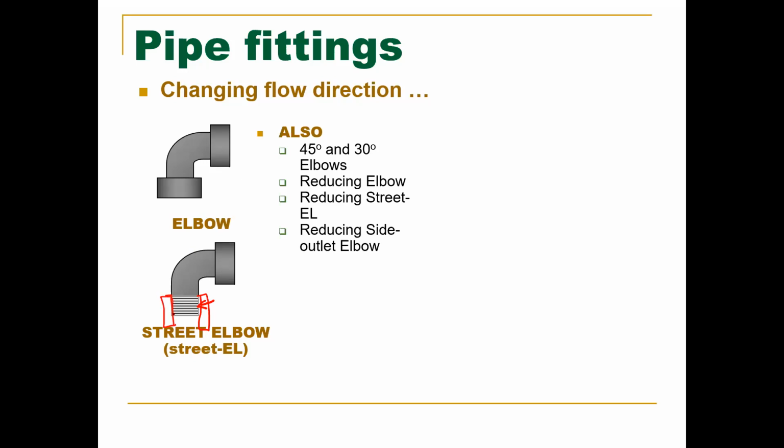This is specifically used in a spot where you don't have a lot of room. Because if you had an elbow here that you had to thread in here, you might not have the physical room to have this outside piece here. This is where a street elbow shines.